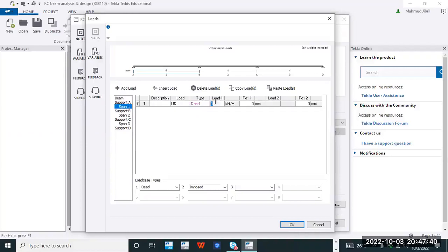And then in this load 1, that is the dead load. What the software wants is only unfactored loads, without any partial factor of safety. Assume we have 10 of dead loads. I'm just putting the values as assumptions, but you as an engineer, when you distribute the load, or you have an issue with any other BIM software like Tekla Structural Designer, ETABS, STAAD.Pro, and so on, or Quick Civil series, you can come here and check and see what it is going to give you.